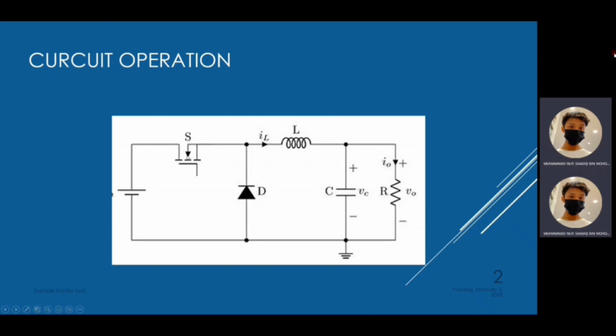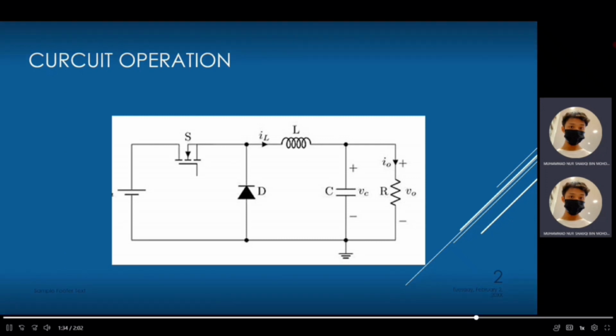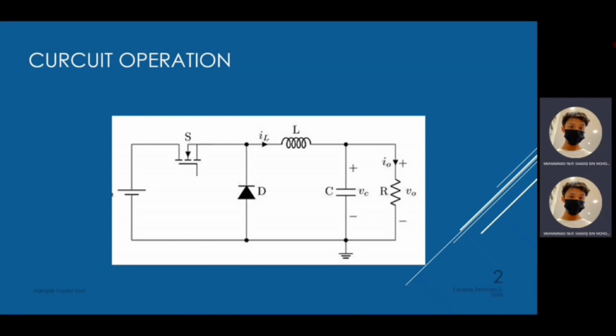When the MOSFET is turned off, the stored current in the inductor and the capacitance source current flow from inductor L through diode D1, capacitance C and the load resistor R. Capacitance C all experience current flow, forming another loop. Until the switch is turned back on, no current flows between the input source and the switch.